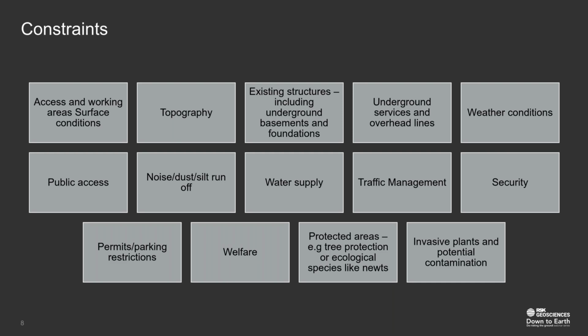When visiting the site, these are the sorts of things that you should consider and look out for. What are the access and working areas? This is going to help you decide which type of rig is suitable for the site logistically. Surface conditions. When looking at access, you should always consider the ground and surface conditions. For example, like the heavy rain we've had recently, is your ground liable to flooding, or is it going to have rutting or make it difficult or impossible to access?